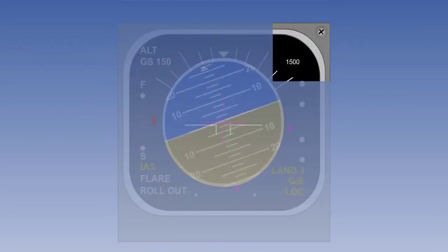Where the display is integrated into an EFIS, it can vary with the manufacturer and the vintage of the electronics. However, a common Boeing format is illustrated here. Below 1,000 feet, the digital readout continues, but the display changes to incorporate a circular white arc, which is graduated in 100-foot increments. The length of the arc reduces in an anti-clockwise direction as height above ground level reduces.